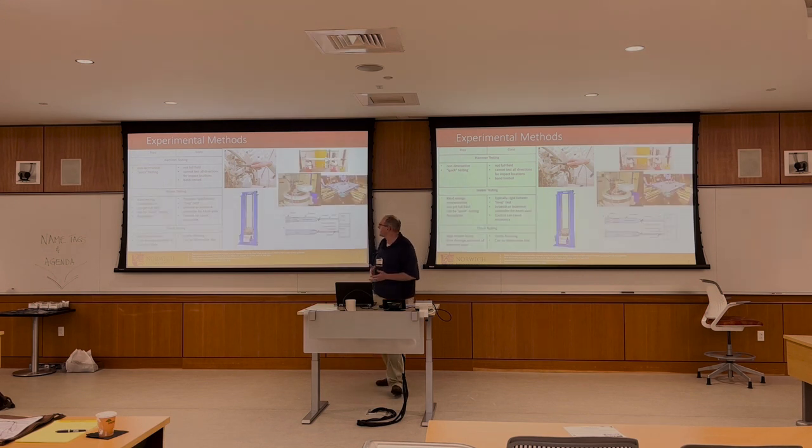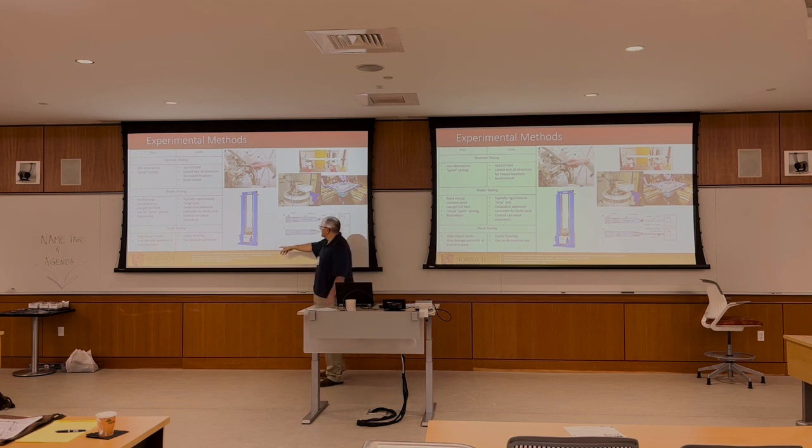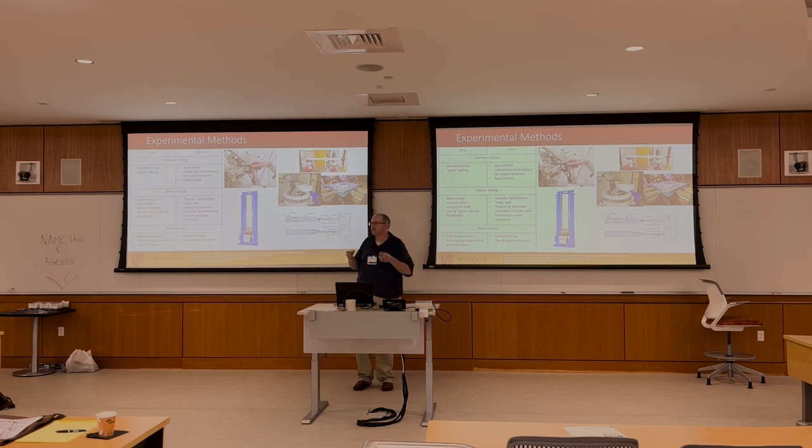So we have many different experimental techniques, such as hammer, shaker, and shock. Hammer and shock, they're nice, but they're typically single one-off things. Shock is actually a destructive test. It's put into this tower that's 20 foot tall, that has 3-inch thick bungees. Those bungees are stretched, and then in those 20 feet, the thing accelerates to almost 70 miles an hour before it hits the ground. So very destructive. And typically your parts won't survive that. But then you have shaker.